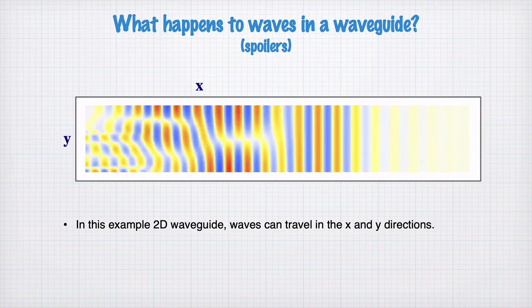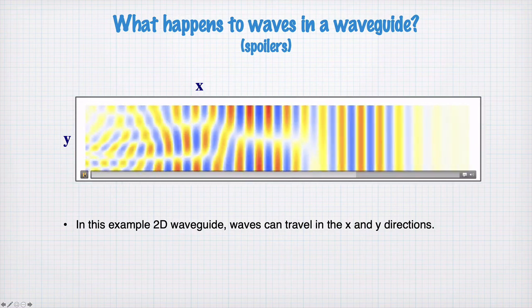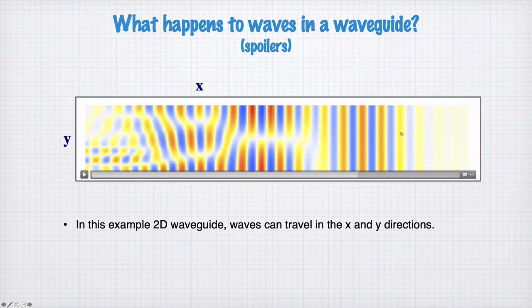And so if I stop the wave motion now, what we see in the furthest along the x-axis, so the waves that are propagating the fastest, are these waves that look like plane waves. They are constant in the y direction and they're propagating in the x direction. So they look like plane waves. That's kind of the plane wave solution. Further back we have a different sort of wave where, if we took a cross section in the y direction, we have a maximum here and then it goes through 0 and then a minimum, and then it oscillates. It looks like a standing wave in the y direction. And in the center of the waveguide we have a node where the amplitude is always 0.